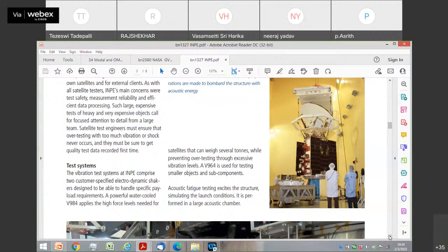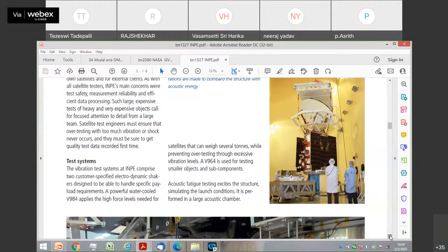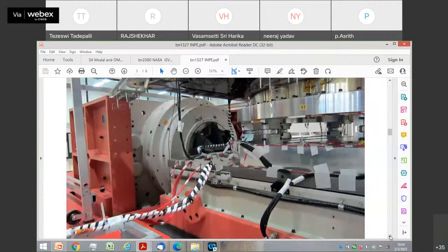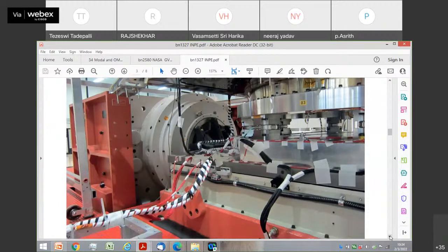In fact, believe me, 15 years back or 20 years back when this measurement started, there was a failure observed on our augmented satellite launch vehicle solar panel. So this gives an idea to the scientists what happens in acoustically induced. Now you have these large facilities in NAL and in ISRO Bangalore, which are 1100 and 1300 cubic meters. In fact, the ISRO one is even with the nitrogen atmosphere for measuring the response of these structures.